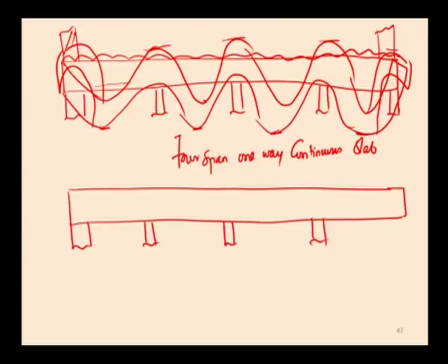This is as per IS 456/2000. Here, 50% of the reinforcement has to be provided as straight bars. The other 50% of the reinforcement has to be cranked over the support and brought to the top to resist the tension which is developed at the support, that is at the top.